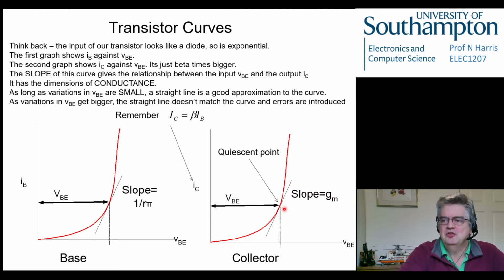Okay, which is effectively the impedance at that point. If we take the slope as being the impedance at any one point, you can see the impedance is varying depending on what position we are on this curve. So that's the whole point of the exercise. If we do the large signal model and put a bias in, we're going to fix it at this point here, and therefore the impedance is going to be looking like this at that set of operating conditions.